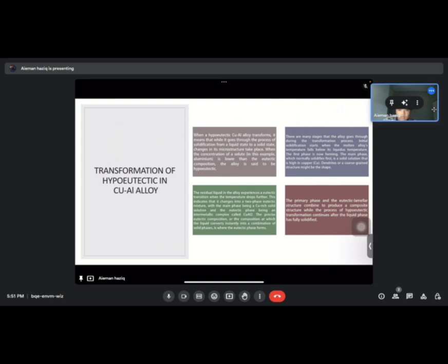When the molten alloy's temperature drops below its liquidus temperature, first solidification begins. The first stage is currently taking shape. The primary phase is a solid solution with a high copper content, which often solidifies first. The form could resemble dendrite or coarse grain structure.